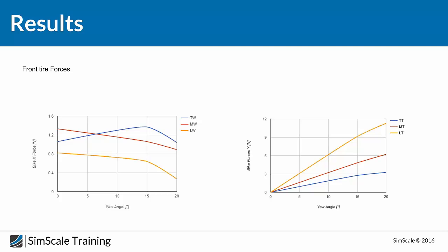Exactly, because in aerodynamics we have two concepts, like you have mentioned right now. Some geometries create more pressure drag, and some other geometries create more skin friction drag. I'm going to give you an example. For bikes, if we take the rider into consideration, 95 to 97% of the drag created by the rider is pressure drag, because of the difference of pressure between the stagnation pressure in front of him and the weak low pressure behind him.